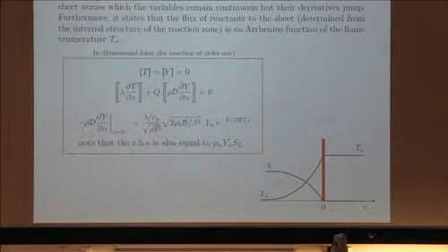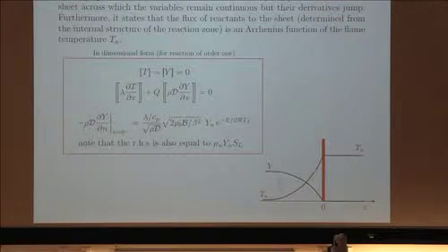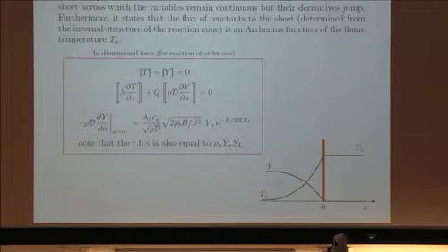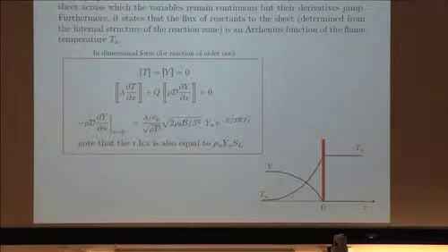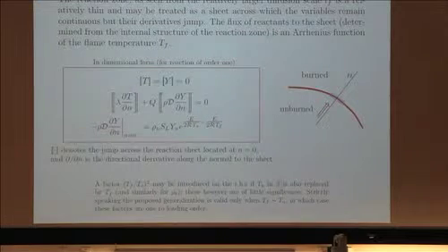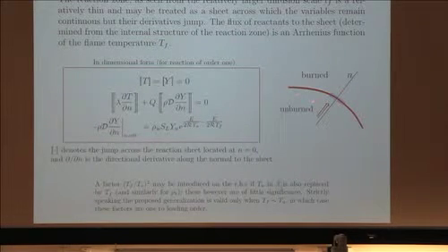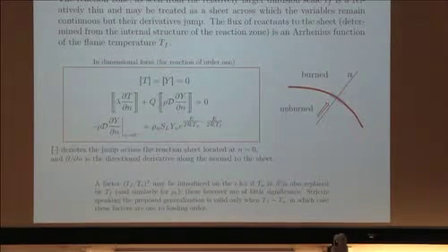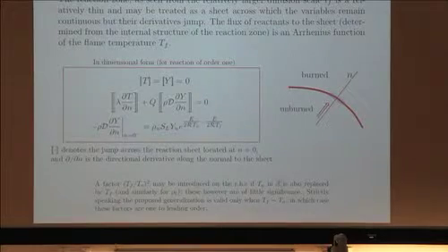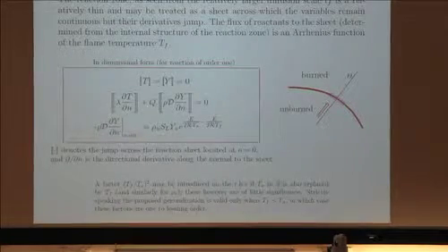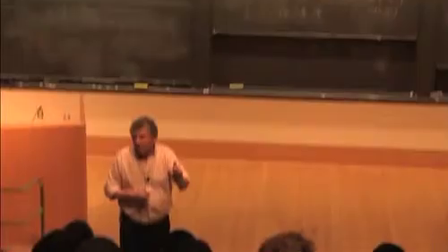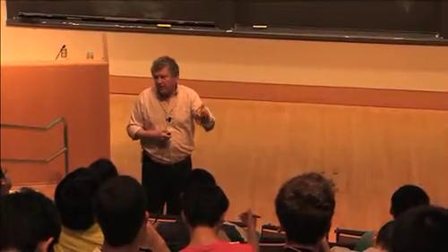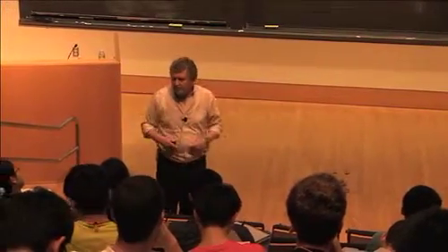So I want to generalize this to flames which are somewhat curved but not flat, okay? We derived this for a planar flame. And the generalization I'm doing by hand waving, but this has been derived systematically, at least for flame temperatures that are close enough to the adiabatic temperature. They don't vary by much.